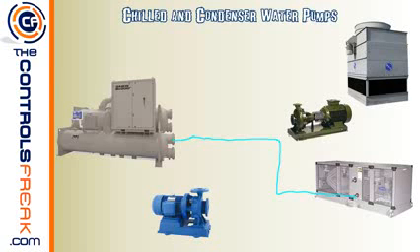And the reason why they do that, and it'll help you identify what piping is what, is that way when you fill this coil with water, you always want to have the outlet of the water coming out the top of the coil. The reason is you want this to fill up with water before trying to pull it out. If you were to supply this coil with water coming in from this direction, the water may not actually fill the coil and you'll get air in this coil, which would mean you're not going to get cooling on the upper portions of this coil, and water would flow in and then come down and get sucked out the bottom. So the reason they fill it up from the bottom is that way you make sure you pressurize the coil and get all the air out of that coil.